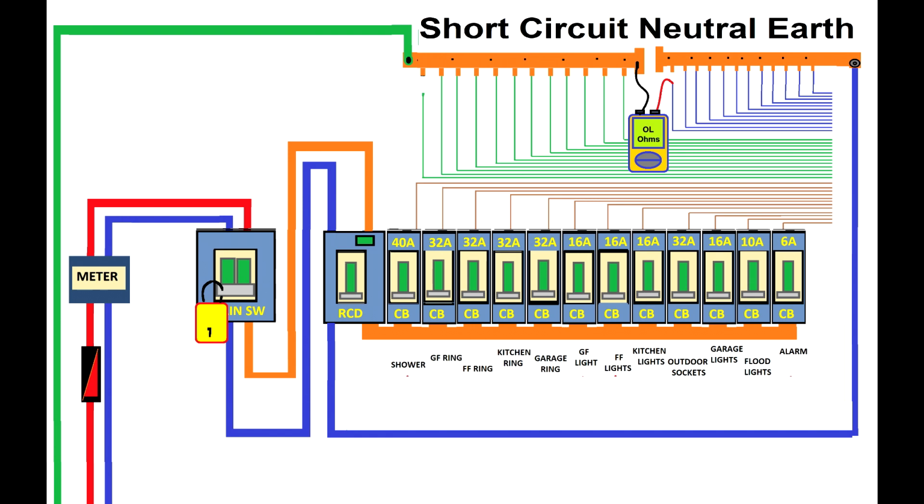In old homes, the distribution boards are nothing but a mess. You look at the wires and you don't know which wire is which. It's very hard sometimes to pair them. So after you realize that you have a very small resistance between the disconnected neutral and the earth, you'll also disconnect the earth, and once you disconnect the earth, you'll realize you have an open circuit. So you're lucky again, you caught the first wire.